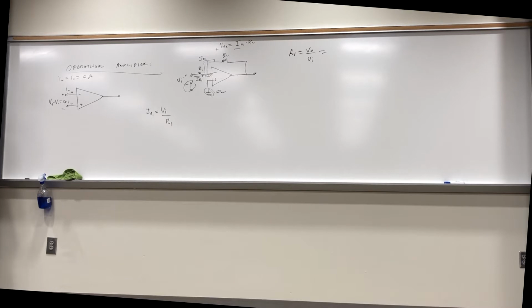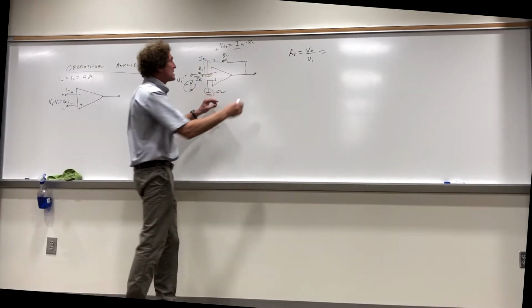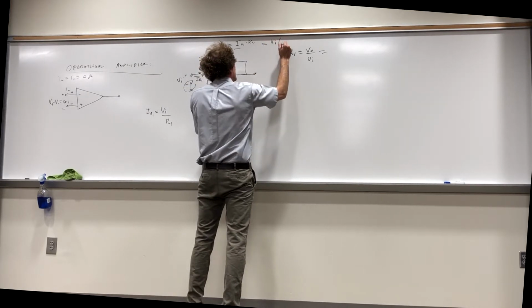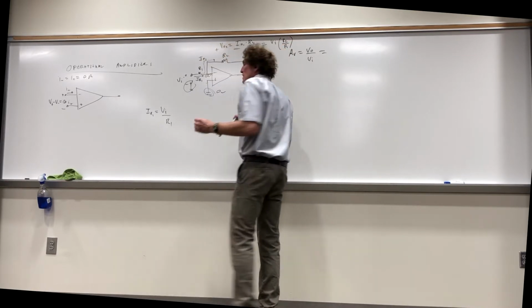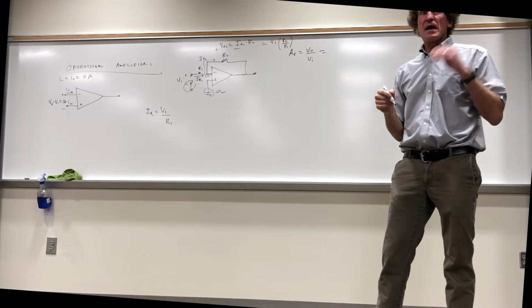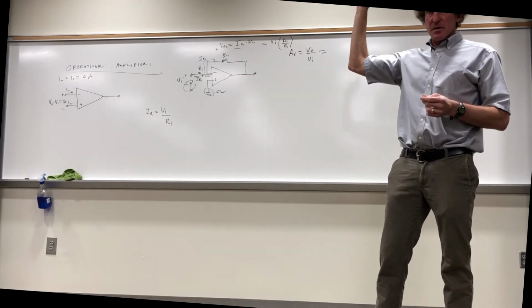You got it? All right, now, what is this voltage plus to minus actually? Well, it's actually equal to what? Vin times R2 over R1, isn't it? Because IR1 was Vin divided by R1, correct? How many see this? Make sure.